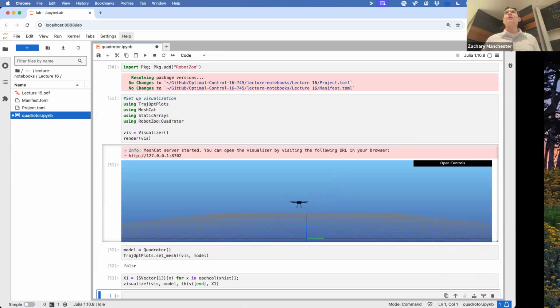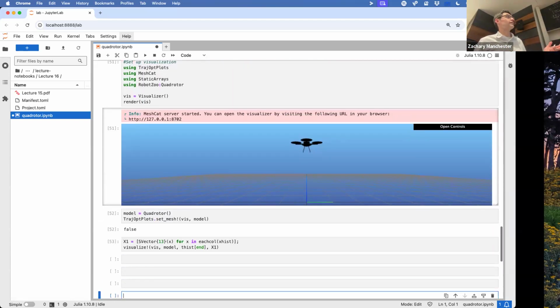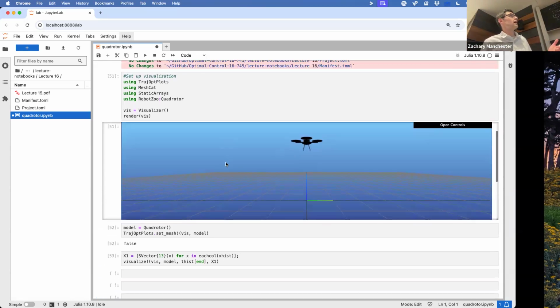You can see these are really aggressive attitudes. So in practice, what would happen here is you would probably hit your torque limits and saturate, and this might fail due to that. But if you put this into an MPC controller that could reason about the torque limits, as we saw with the planar case, it works super, super well. You can do really wild stuff with this, really far away. Keep in mind, this is an LTI model linearized about hover, right? So it's a single model. There's nothing in there that's really nonlinear. And I'm running this on the full nonlinear model. And it's doing really well with these really wildly off initial conditions.